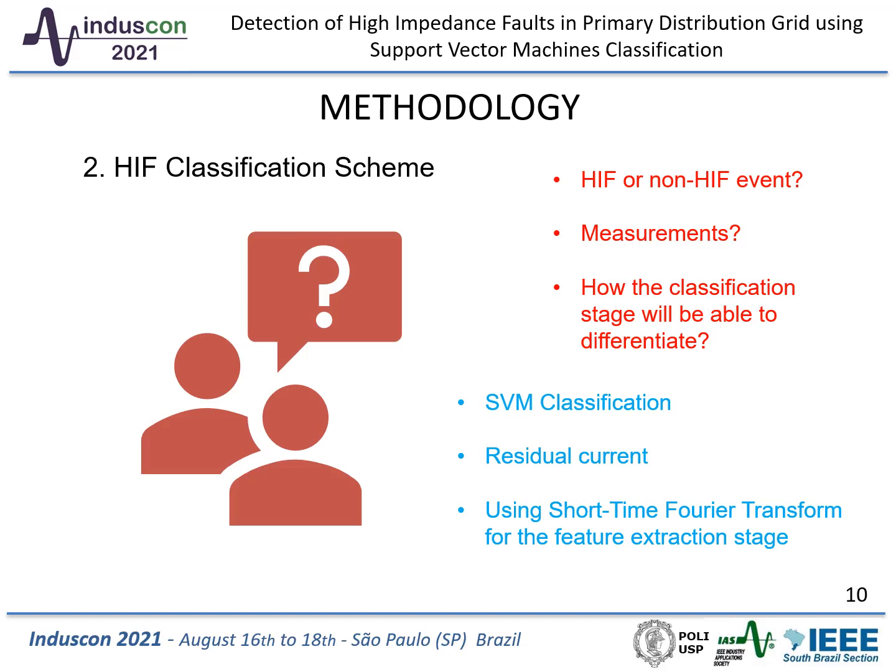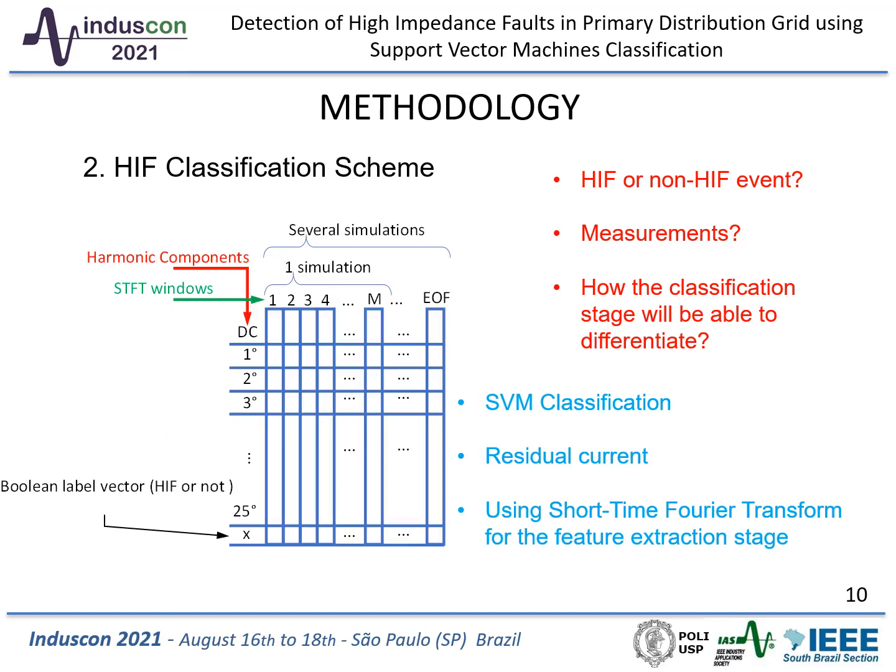The short-time Fourier transform is used for the feature extraction stage and is responsible for dividing a signal into several smaller segments of equal length, applying the conventional Fourier transform on each of these segments individually. From there, feature extraction obtains new features by transforming the original input signal. On the other hand, feature selection is achieved when a certain number of relevant features are chosen. In general, it is important to consider using the lowest number of features possible.